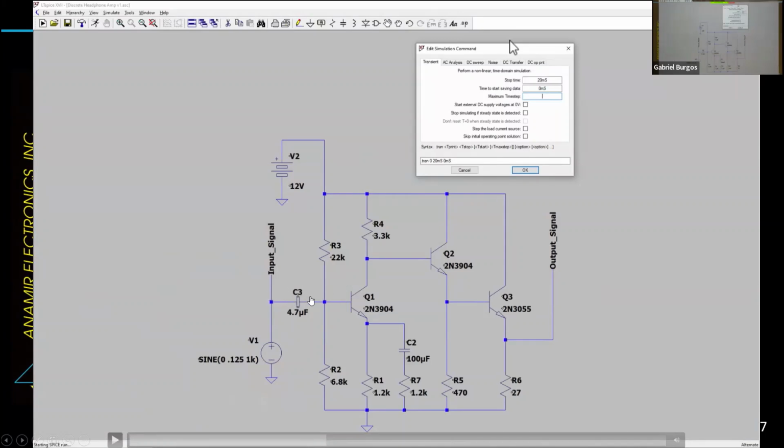This blocks the DC, so the DC can develop for the transistor, but there's no DC on the microphone, because the DC would ruin the microphone's performance. So we have a capacitor blocking the DC. The AC gets through, and then we have two resistors that provide biasing for that transistor. So the transistor is biased in an on condition; it's always on. The 0.6 volts is not a problem because you provide voltages that make the transistor turn on all the time.